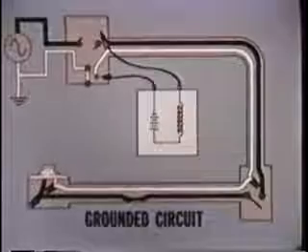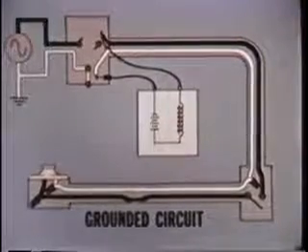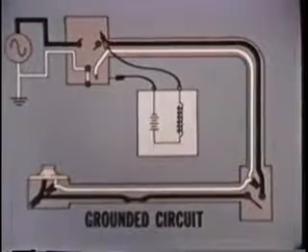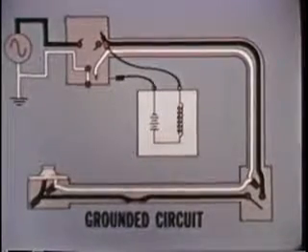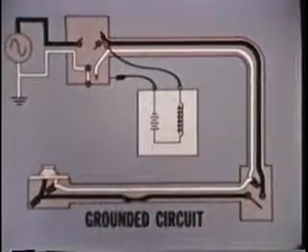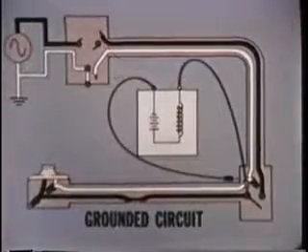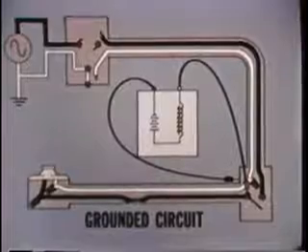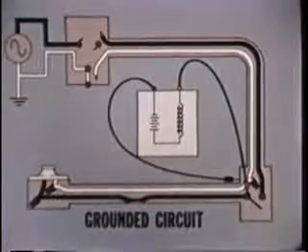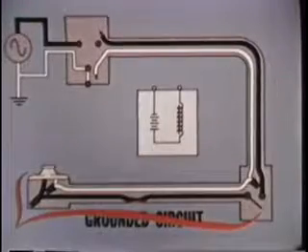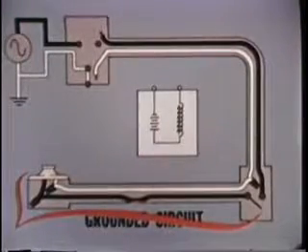First, checking between the two conductors indicates that there is no short circuit in the first section of the circuit. And there is no continuity between the hot conductor and ground in this section. However, between the hot conductor and ground in the second section, there is continuity. Since this is the last section, the testing is complete.